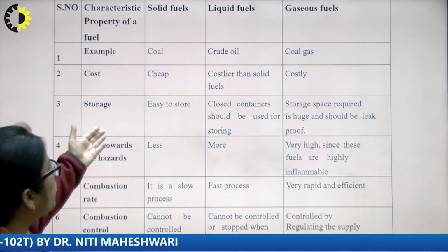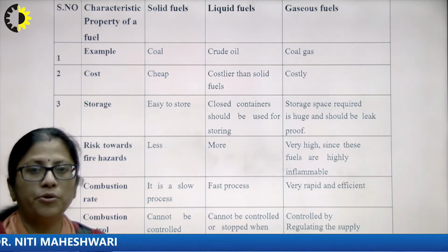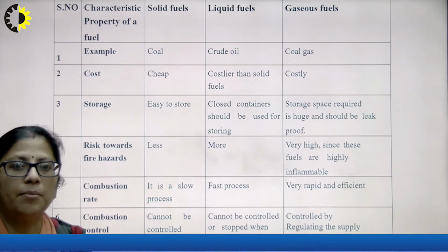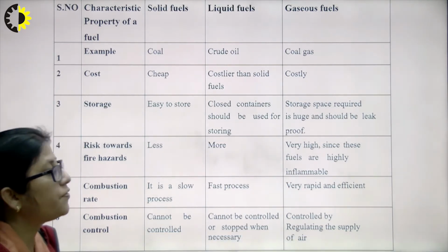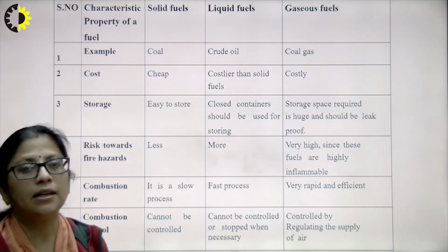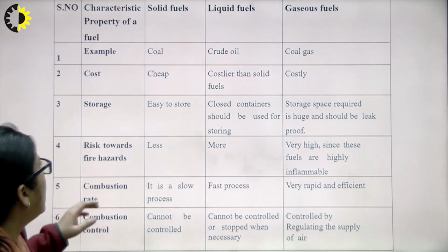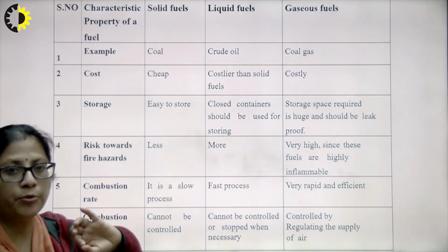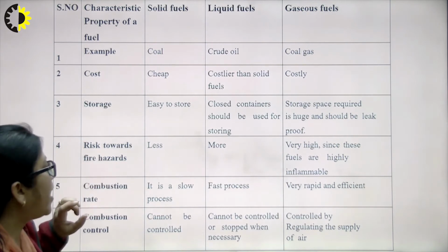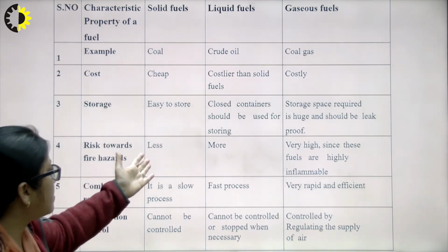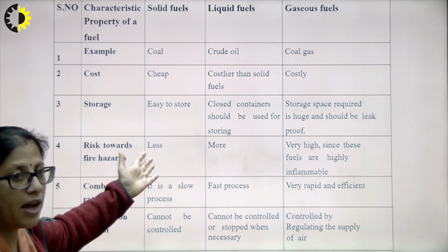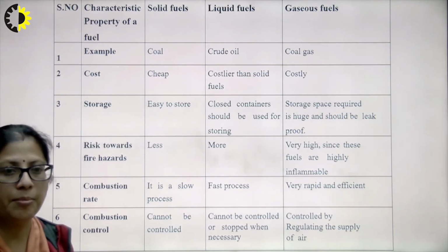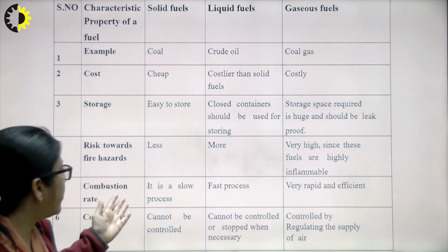In terms of storage, solid fuels are easy to store. If I have coal or wood, I can put it at any place and store it. But liquid and gaseous fuels ought to be stored in containers, and for gaseous fuel, those containers should specifically be leak proof. Regarding the risk of fire hazard, solid fuels pose less risk, liquid fuels more, and gaseous fuels are highly inflammable.